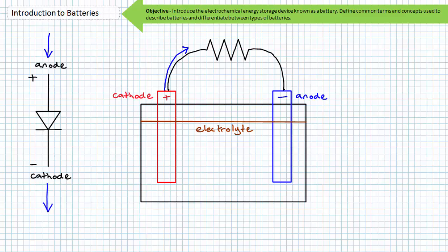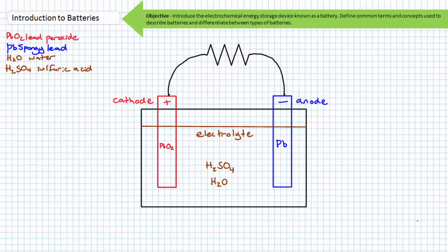An anode is defined as the point where conventional current enters. Conventional current enters the anode of a battery in the return loop of the circuit when the battery is supplying conventional current, just as conventional current enters the anode of a diode when the diode is forward biased. These definitions only extend to the functionality of the electrodes external to the battery during discharge, because, as we'll see in a moment, there is a charge movement internal to the battery, and the direction of current is reversed during the charge process. I don't wish this lecture to devolve into a chemistry lesson.